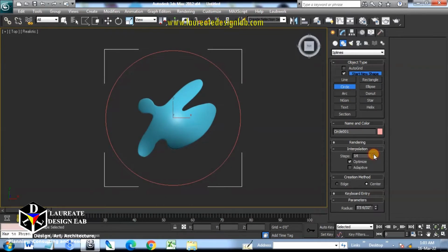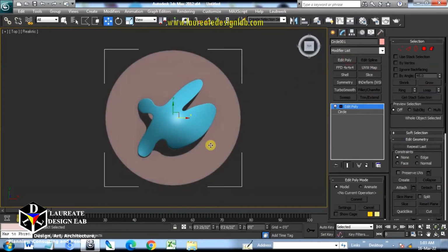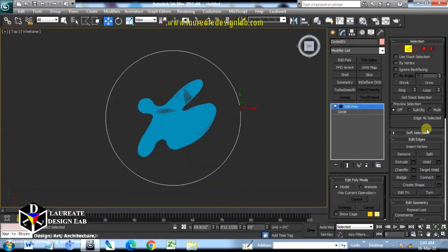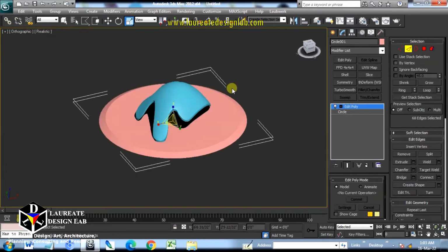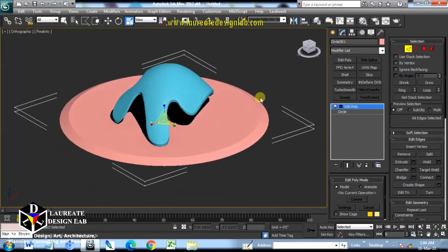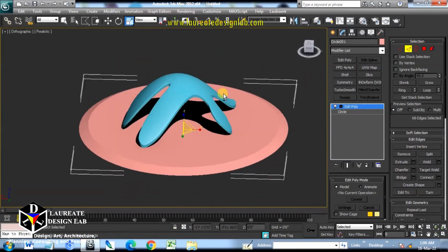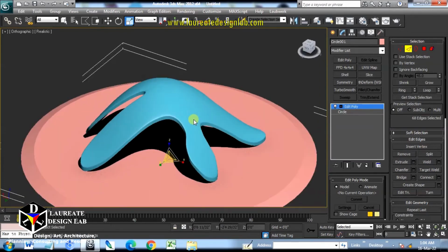Most of its parts, if divided by a grid, give a monolithic structural impression. Long span structures can be built using flat construction such as heavy girders, trusses, and space frames. However, for spans approximately 30 meters, it is often more economical to build a system made up of curved members.